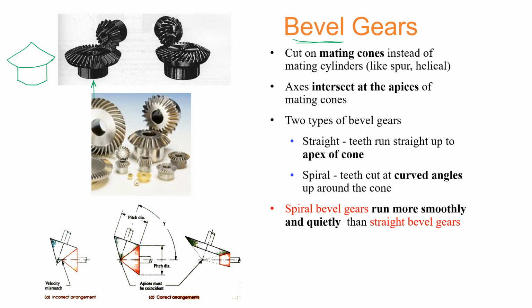Now you can assume that the top cone has been truncated from the top, and the remaining surface is where you have carved out the gear profiles. And that's exactly what is on display over here. Now this is one of the gears. The other gear is also going to have a cone-like structure, possibly a truncated cone, and the point of intersection is going to be an important point because that should coincide right over here at this point. And this point is very much clear in this diagram.